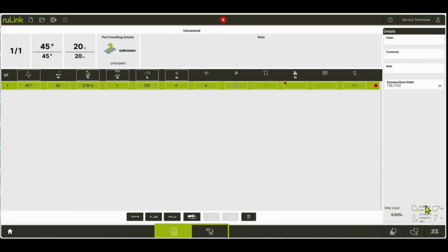Okay, and so now what will happen when you get on that line and you put that open hem in there, the jaw is going to come down and clamp to about 0.180. It's just going to be tight enough to hold it down, right? And it's going to look here and say, yep, you've told me this, but I also know this here. And it works with those two pieces together, so that you don't get an alarm for a material being too thick. Okay. All right.